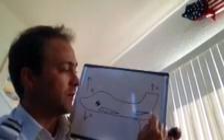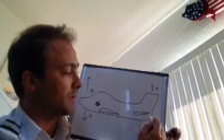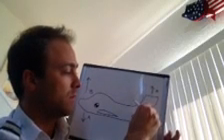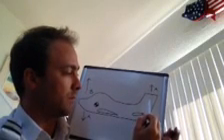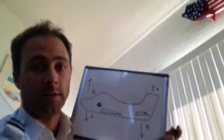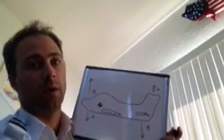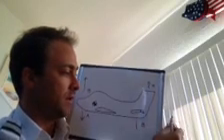What this is doing is actually projecting itself into the relative wind, which is causing this flight control, the elevator, to be deflected downwards. What this is doing is it's decreasing our angle of attack. It's decreasing the amount of tail down force that we have in the aircraft. So it's taking this tail down force and it's decreasing it.